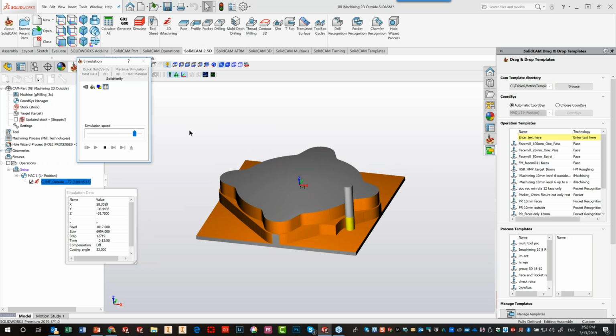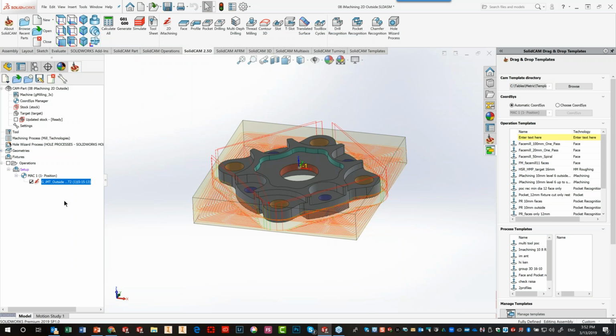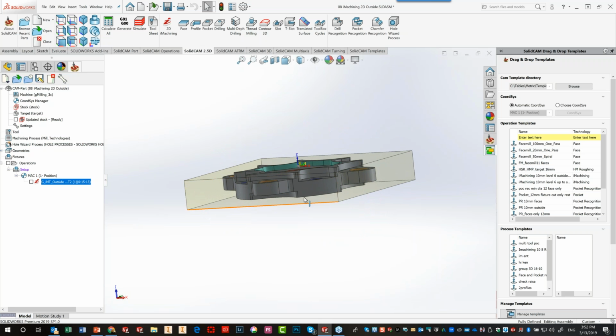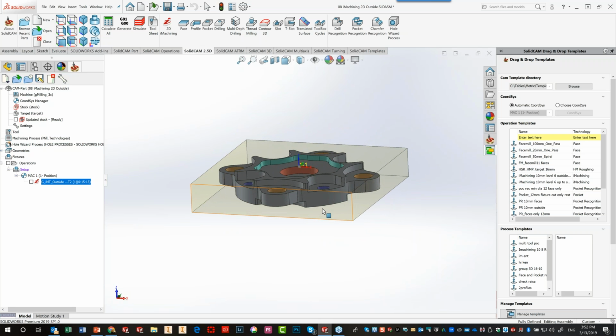Now, by the way, if you would try to do this in the old classic way, you would have to make your first geometry on the outside of the stock area and say that that was open. And your second geometry, your second chain would be almost impossible to pick. Not impossible, it would be very hard. Because if you note, there's no really one constant Z over here of the chain going all around. So you have to go from edge to edge. It was always a nightmare creating the geometry for the outside perimeter. But now it will automatically recognize the outside perimeter.